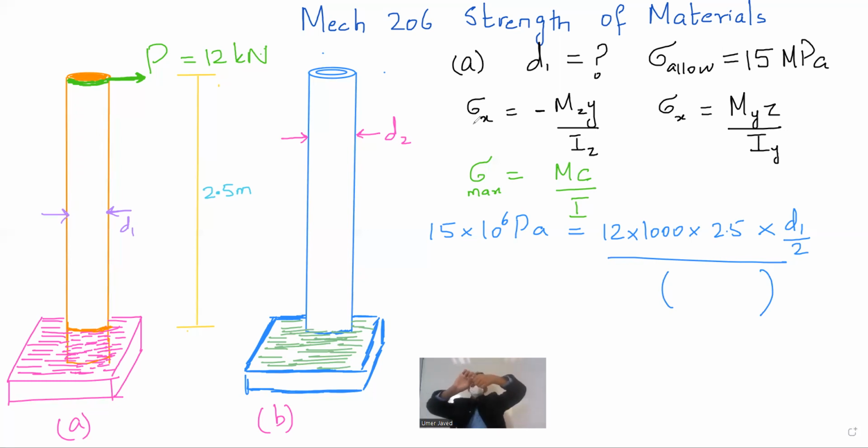Okay, look, for the torsion problem, I used to do like this. Shear stress equal to TR over IP, right? Remember that? TR over IP. So I used to do like this, like this. So this circular section used to resist. That's why a polar moment of inertia, IP, used to come in the denominator. Agreed?